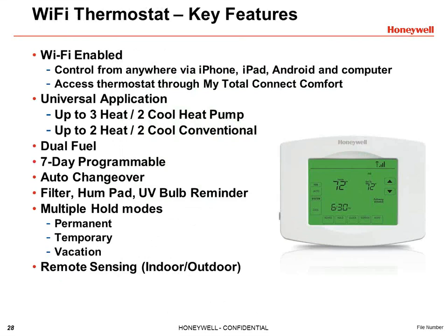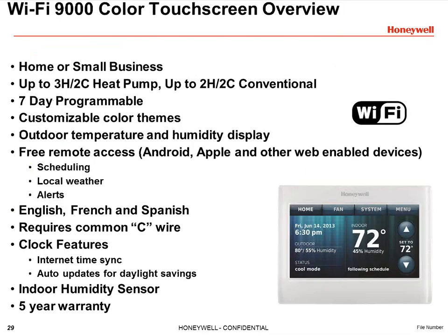So when we're talking about the Vision Pro thermostat, it has the green screen, it's touch screen, but now what we're getting is, you know, a true 7-day, we can do auto changeover, we're getting built-in reminders, we're getting a little bit more out of the thermostat than the standard Focus Pro. But really what it boils down to is you went from a small push-button thermostat to a large touch-screen thermostat. That's really the biggest difference in the thermostats.